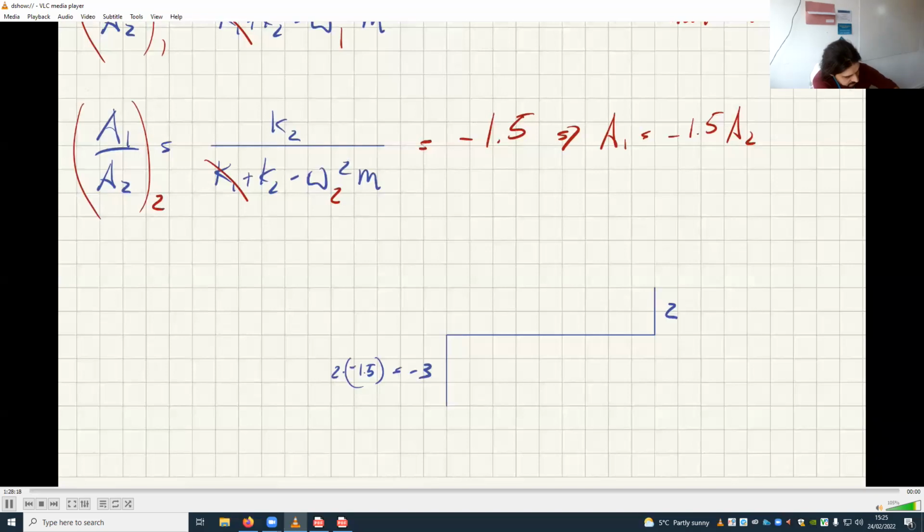Okay. And so this is the mode shape. And that means in between these two, there is a node here, for which the amplitude is 0. So if I twist this in this way, there is one point on the shaft that doesn't twist. That's what I'm saying. And again, the fact that I've chosen these two is completely arbitrary. Because if this is 1, this is minus 1.5. If this is 4, this is minus 6. So it doesn't matter.